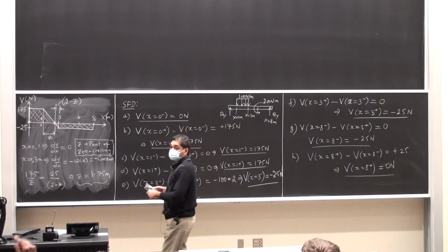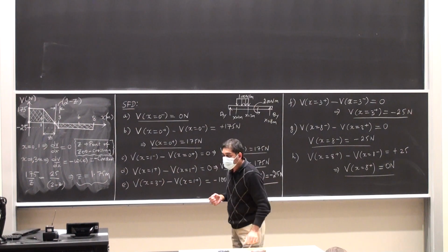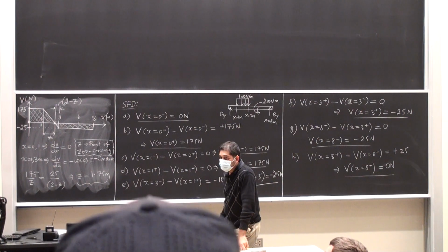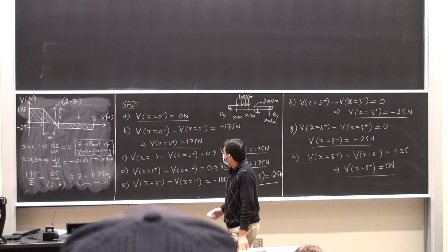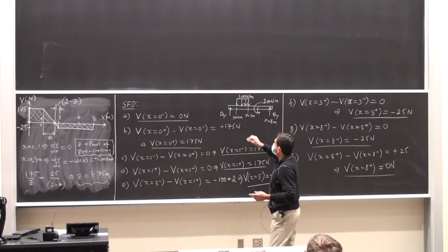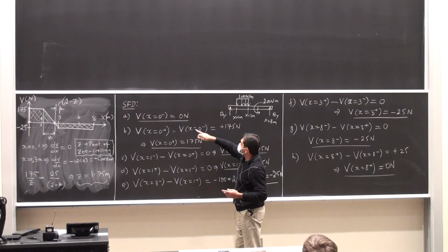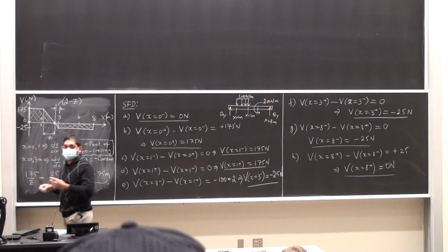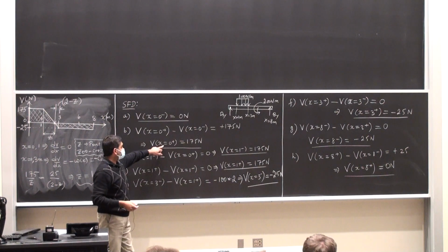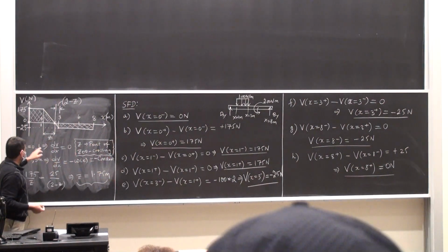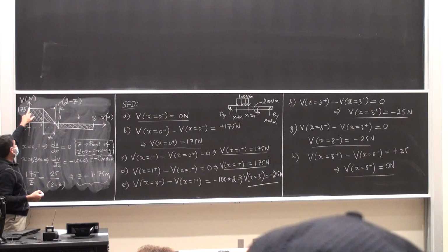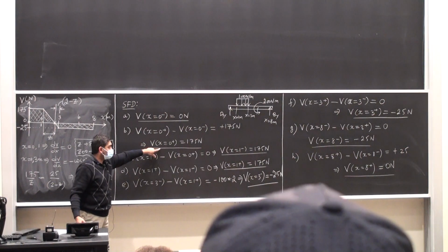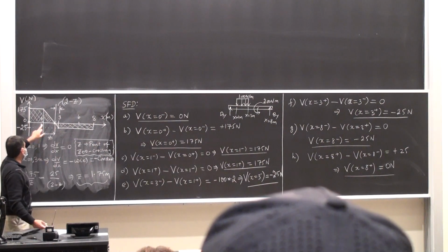Yes, you want me to go over the direct relationship between the shear diagram and the figure? Right, so I'm starting here, which is why I'm using this particular value. That value is marked as a 0 here. Then I'm going to the next step, which is x at 0 plus. So I'm still at 0. I'm climbing from here by an amount of 175 newtons. Then I'm going from 175 newtons to x at 1 minus, which is right here.